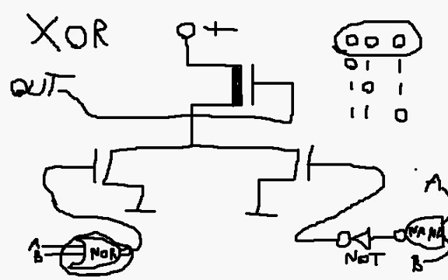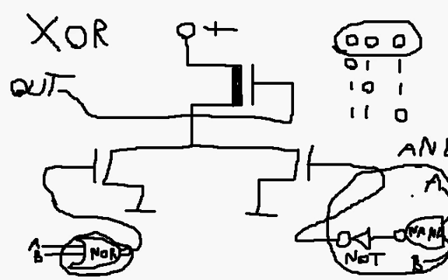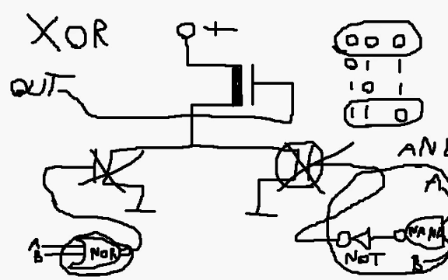Conversely, on this side, this has the net effect of being an AND gate, because it's a NAND gate that goes through an inverter, so that basically gives you AND. I'll just circle that whole thing and say that's AND, because that's essentially what it is. So that gives you this case, and once again, if 1 and 1 are both true, then that activates this MOSFET here, and that again pulls the output down to ground because this MOSFET is now conducting to ground. If neither of those are the case, then this doesn't turn on and this doesn't turn on, and then the output stays high, and that gives you these two cases here.